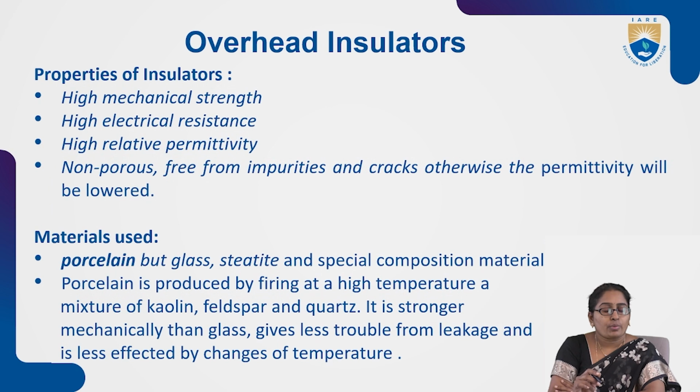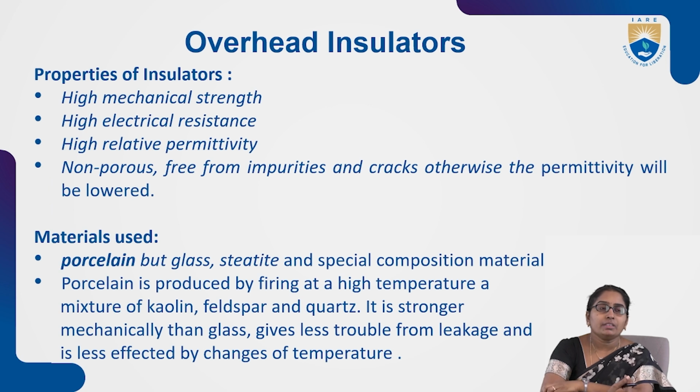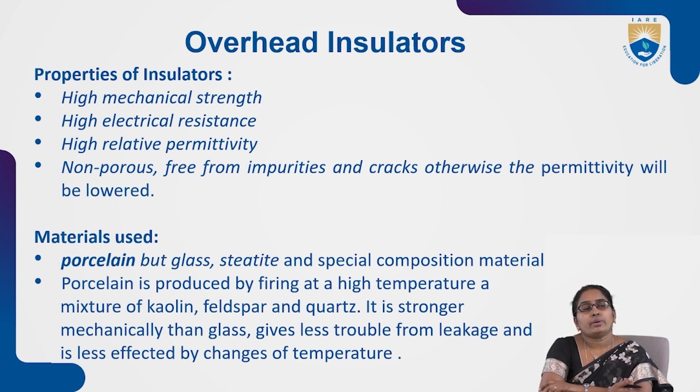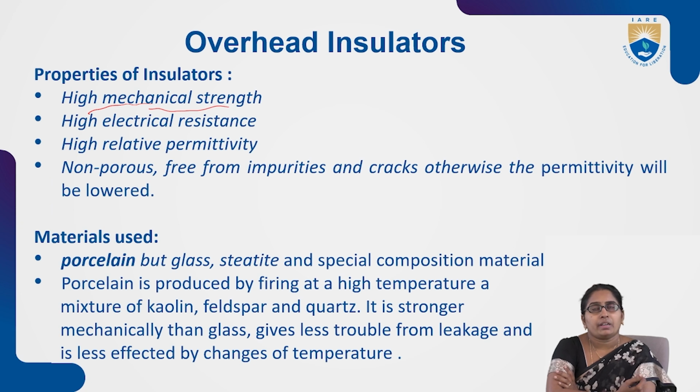Okay, next, properties of the insulators. First, high mechanical strength. The insulator must have high mechanical strength and high electrical resistance, right? The insulator, whatever is provided to insulate the conductor, must have high mechanical strength to provide support to the suspended conductor.